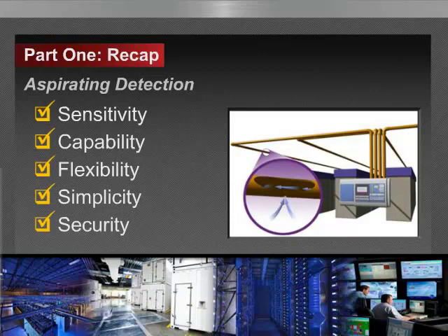So once inside the detection chamber, a laser light scattering technique is used to determine the amount of smoke present in the air sample. So a properly designed and commissioned aspirating smoke detection system overcomes the challenges of dynamic environments, meeting performance objectives by the nature of their operation. Advanced aspirating smoke detectors detect fires at their incipient stage, allowing early intervention for investigation and action, potentially before smoke and corrosive gases affect equipment and personnel.